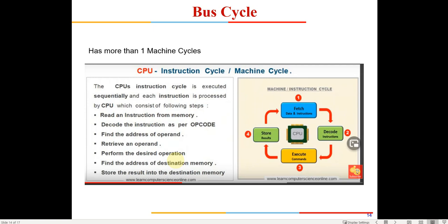First of all, the contents of the BX register are to be taken, then the address being pointed to by BX, and the information is to be taken from there. Or if you write [BX plus 10], then the contents of BX are to be taken and 10 is to be added to that. Then, whatever the result, the physical address is to be computed accordingly, the data is taken from there, and then it needs to be stored.